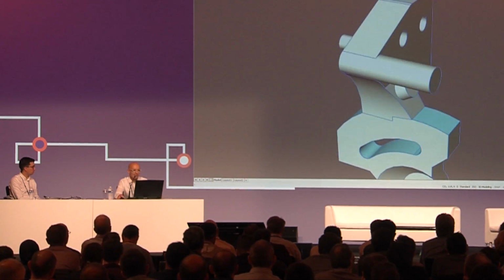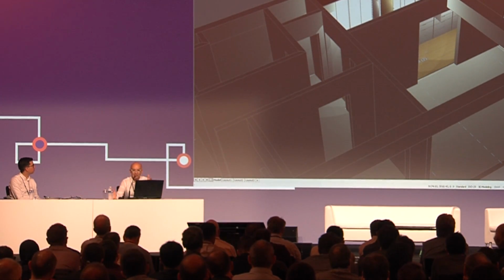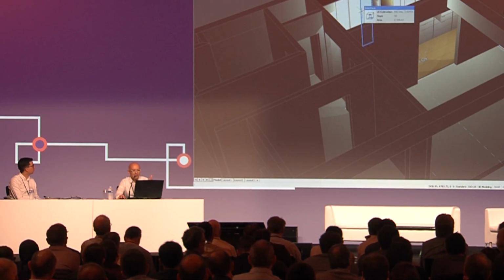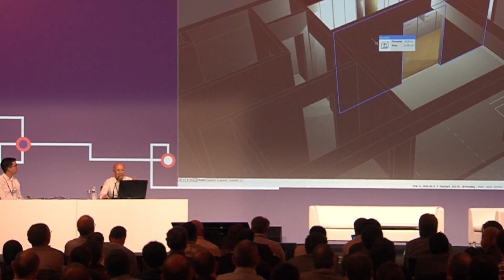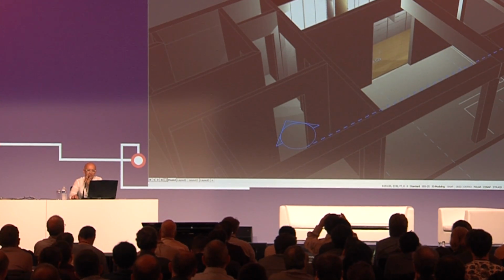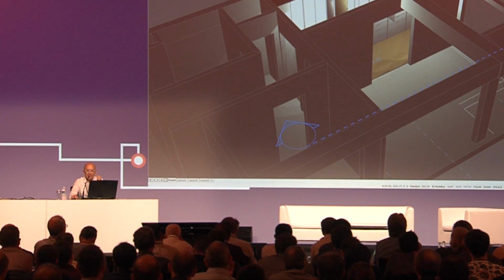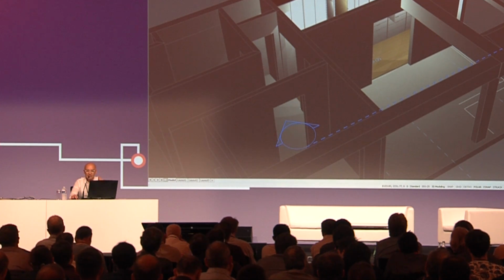But sometimes you will get into a situation where you have this clean screen. There's nothing of the user interface that is in your way, but still, I would like to start modeling and modifying something here in that drawer, that wardrobe. So what is the BricsCAD answer to get things out of the way? It's not changing layers and layer states or isolating entities. No, it's like here. And by the way, you see that currently I am modifying a property in place, so you do not need your properties panel all the time around.